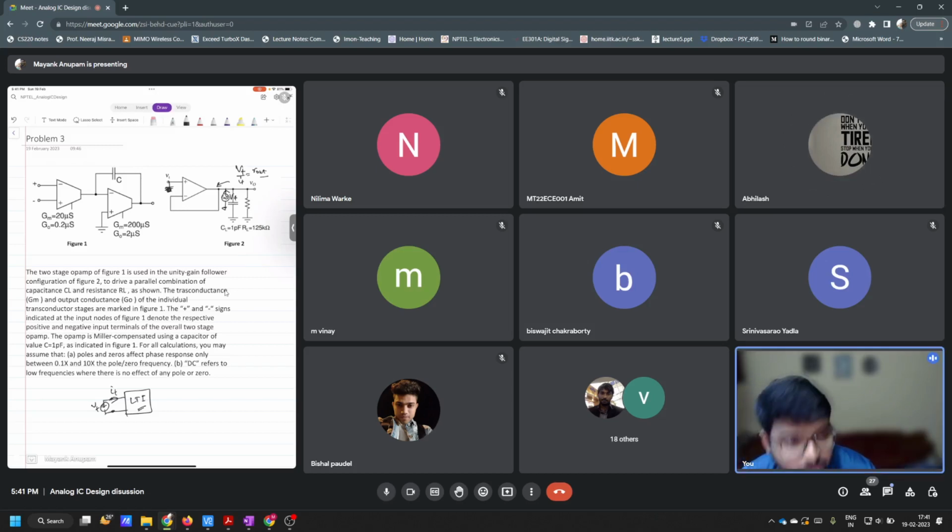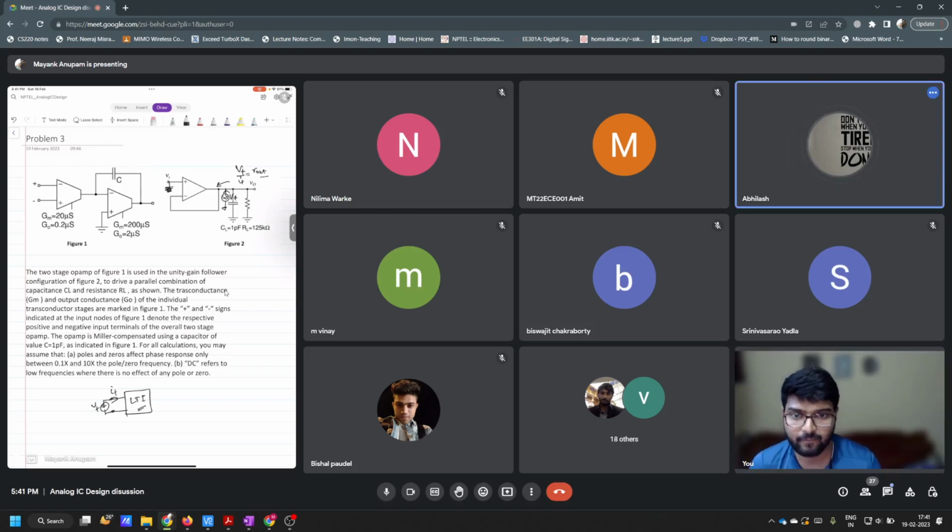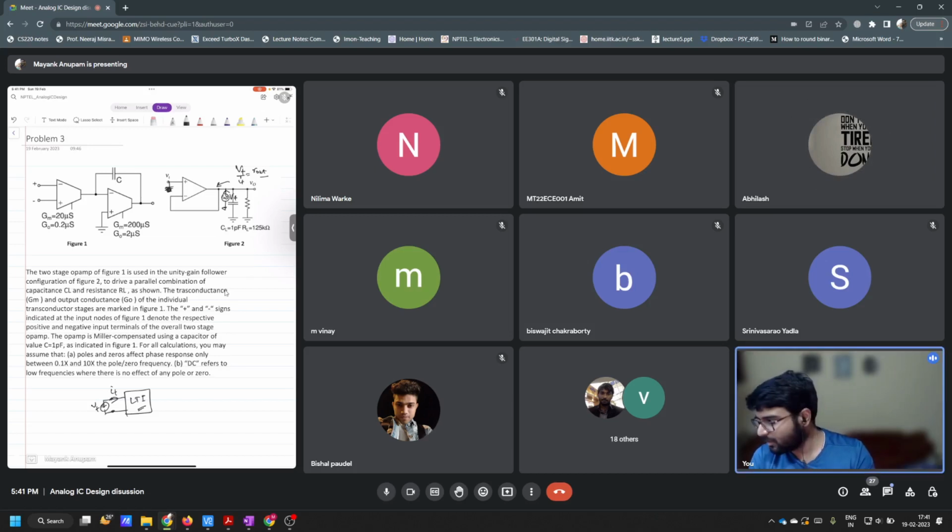So that is how you have to do it. Yes, sir. So in the question, be mindful what they are asking. Whether they are asking only the output impedance of this part, or they are asking the output impedance of everything. If they are asking everything, that means you also consider these two guys here. If they are asking only the output impedance of this op amp, then you have to ignore these two guys here. I mean, while calculating output impedance, you remove these two from the calculation. So that is how you calculate output impedance.